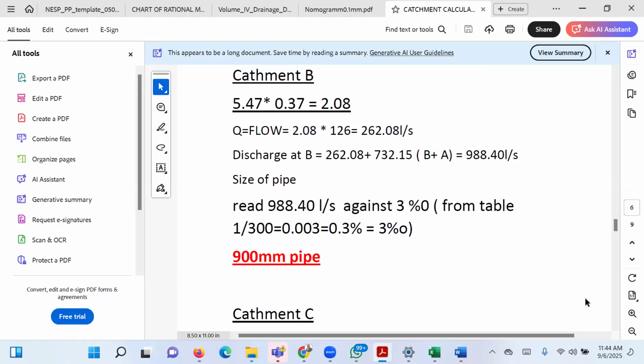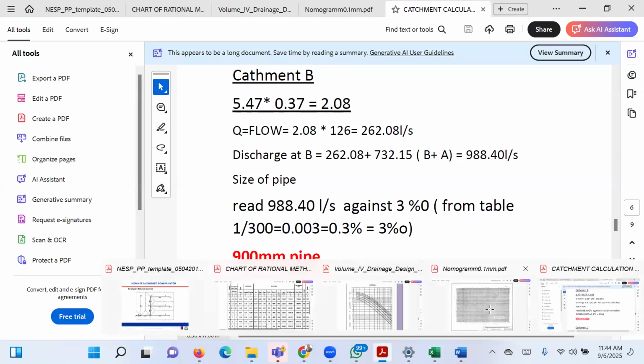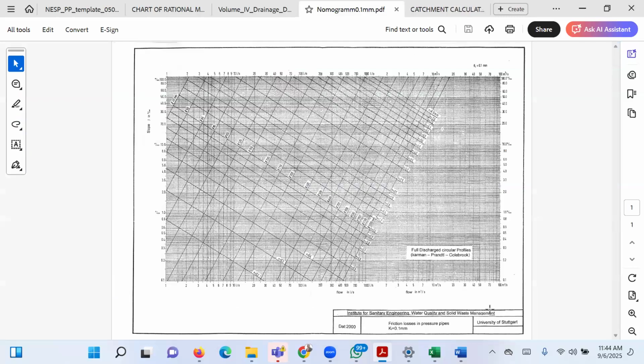Yes. Okay, look, in the beginning, you said 3 factors: the pipe roughness, the slope, and the discharge. By using these charts, we have fixed one. You know, these are 3 unknowns. So we need to fix 2 and look for 1. Go ahead. Okay, so we are getting the slope from the surveyor.